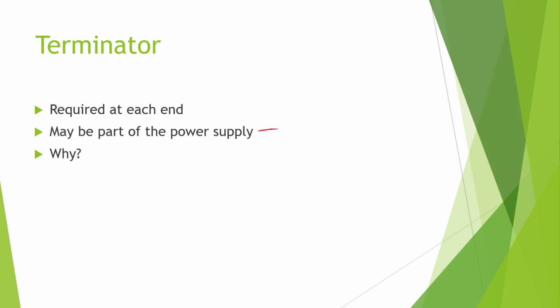My notes say that if you only have one, it may appear to function properly, but it's going to have distorted signals, increased amplitude, and greater susceptibility to signal reflection noise. So really make sure you have both. My notes also say we're going to have a 100 ohm resistor. That is what the notes say.